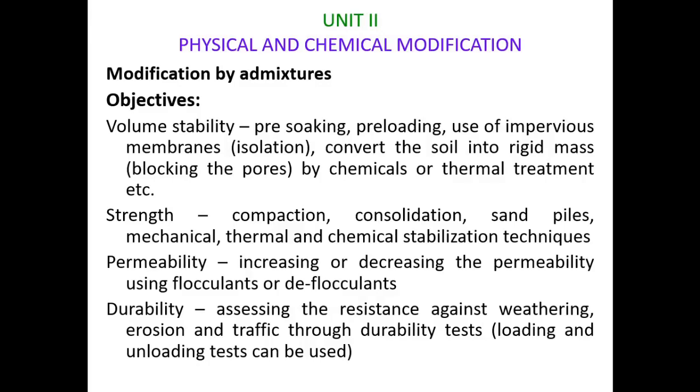the density of soil. The common methods to improve the density of soil are compaction, vibroflotation, sand piles, lateral consolidation, and using additives. Other methods to improve strength are chemical and thermal stabilization. Densification is always useful in improving soil strength, even if another stabilization method is employed. The next soil property is permeability.